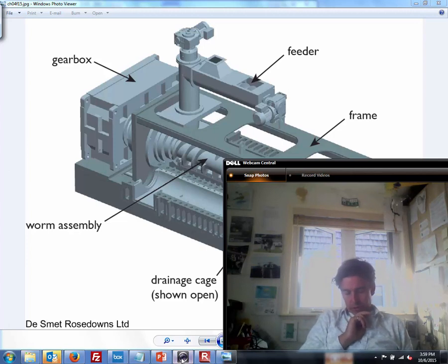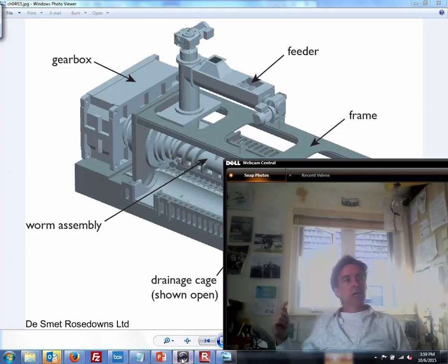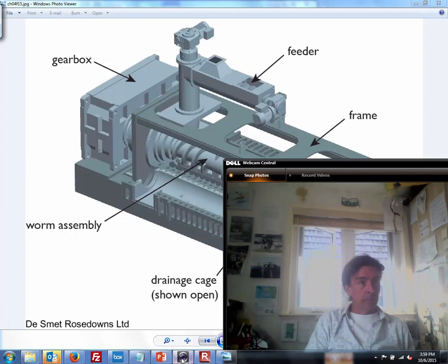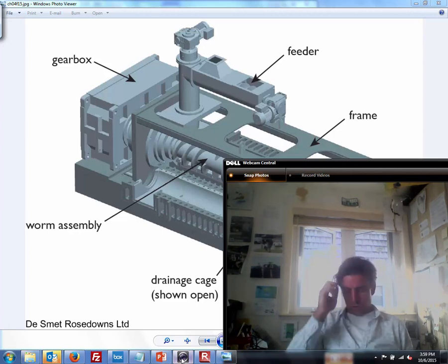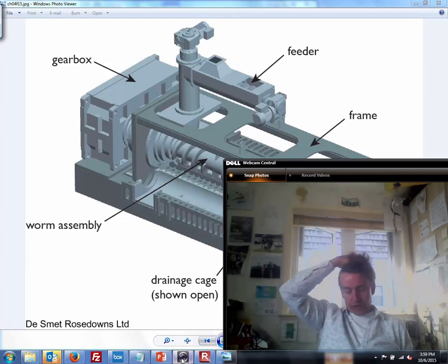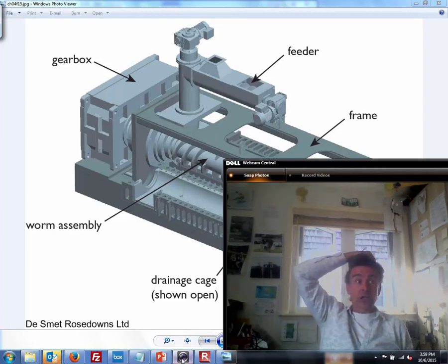Okay, let's take a look at water gas. It says the basic low temperature gasification, so again, solid to gas, might leave a residue of char, mostly carbon, not a bad thing, similar to coal. This can also then be gasified by burning it at a very high temperature and injecting steam. So you're actually putting H2O into the process. Kind of cool. This temperature is sufficient to break the steam into hydrogen and oxygen.